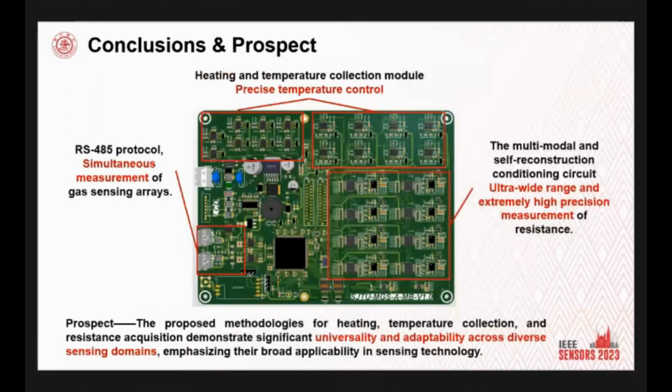In this study, a universal data acquisition system for flexible and MEMS-based gas sensors is designed, and the highlight of the system is that it is compatible with both the MEMS and flexible gas sensors. Combined with the heating module and the temperature collection module, temperature control can be achieved, like the PID temperature control for flexible gas sensors. The core component of the system is the novel multi-module self-reconstruction conditioning circuit, which can achieve ultra-wide range and extremely high precision measurement of resistance of gas-sensitive material.